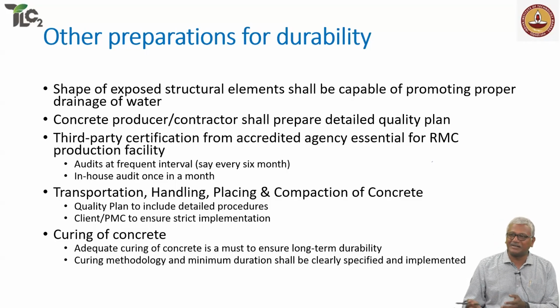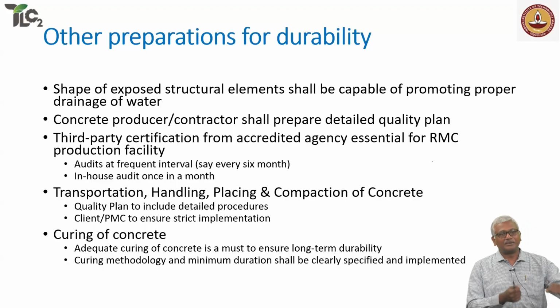Rainwater harvesting is not intended to be done on floors. It should be done in wells. Unfortunately, it used to be done on our floors. Water was available all the time, and there was no way to drain out this water unless you start using manual labor. That's not what you want to do, right? You want to design appropriate slopes at your terraces wherever water is likely to collect, to ensure that water drains out. And that's the first principle of durability, to design your structure so that water does not stay on in the structure, it goes away.